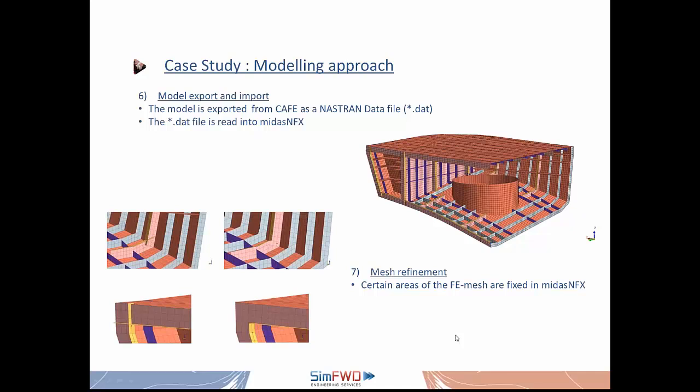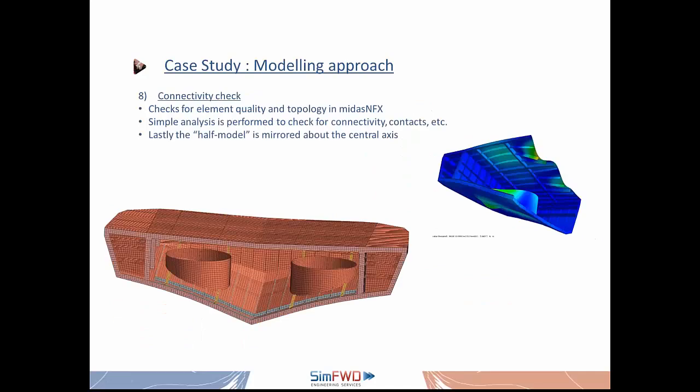So after we have done a first round of refining our mesh and checking the connectivity of the elements, we have also utilized the tools within Midas NFX to check the element quality and the topology of the mesh.